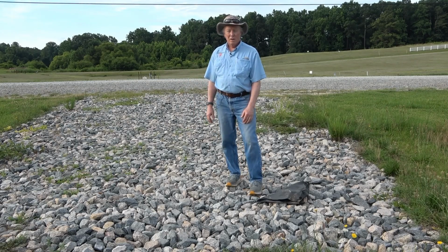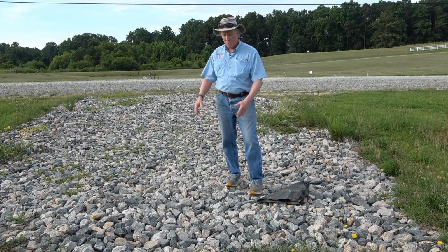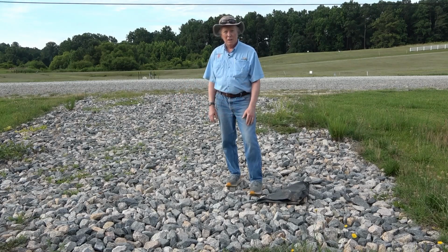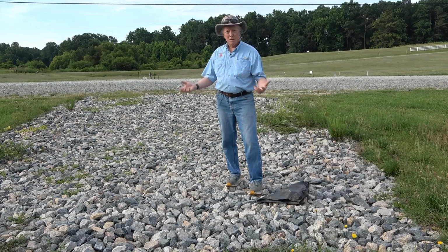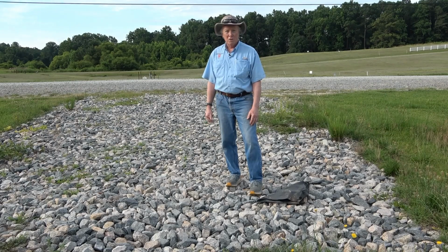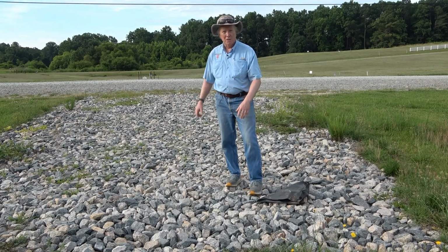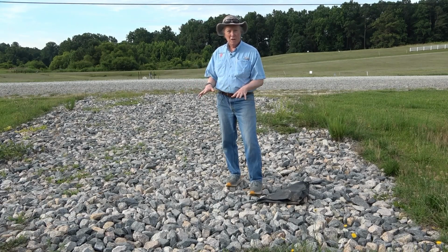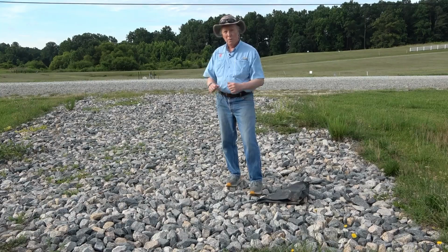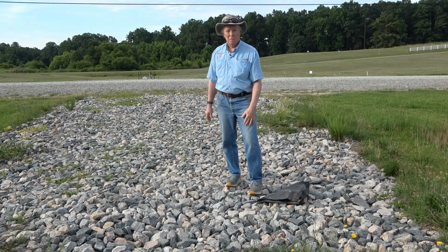And then lastly, the most expensive system, but also probably the most effective, are these commercial wheel washing stations that go in right by the roadside, and as the truck pulls through it, pressure washers get the undercarriage, they get the wheels, and are very effective. Generally, people are using those in very tight situations where they don't have room for something like this. Either way, again, make sure that you have some system in place to get the mud off the tires of the vehicles before they get out onto the public roads.